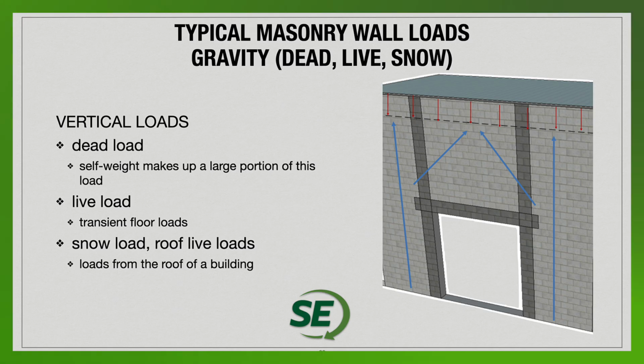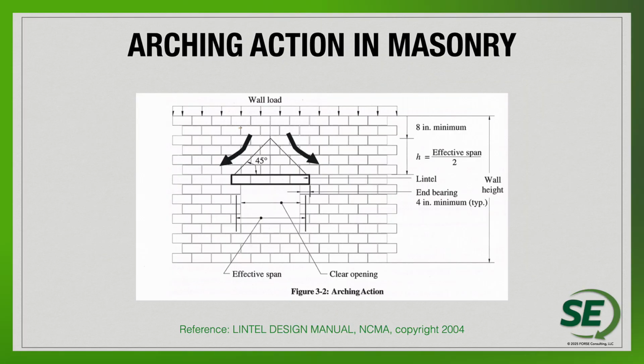to want to support those forces based on stiffness, and really that's going to be, as long as we have continuity or continuous elements from the area above the opening to each side, we have the ability to consider something like arching action. So there is a document from NCMA that has a nice little diagram in here for looking at the forces on a masonry lintel when we have the ability to consider arching action. So that's going to be a pretty important aspect of it,